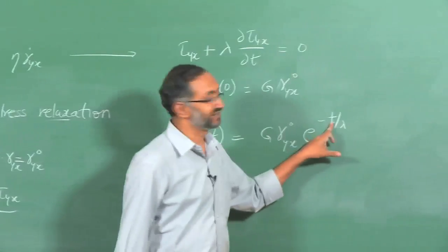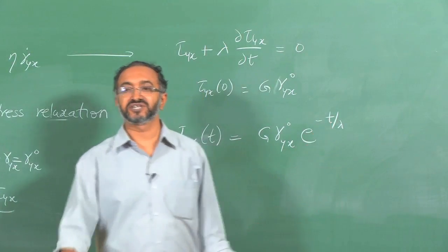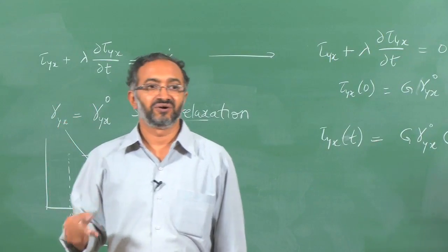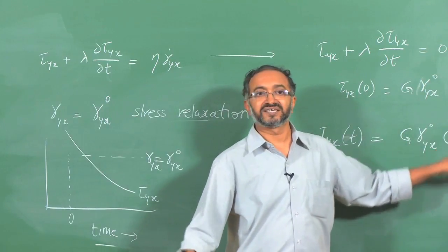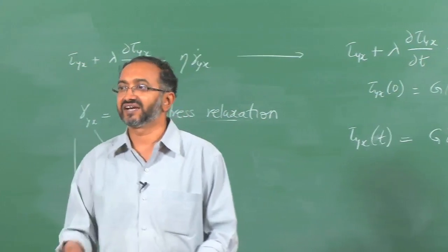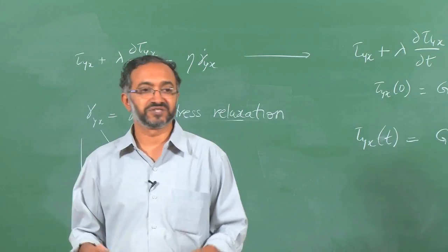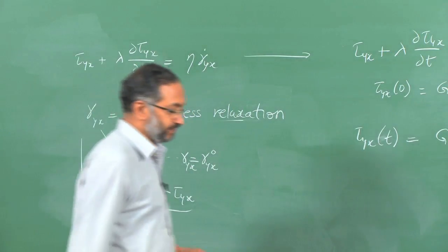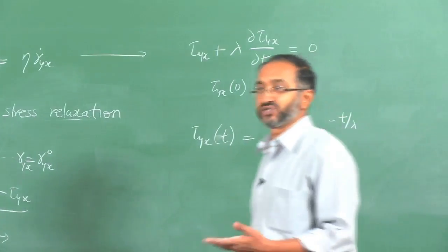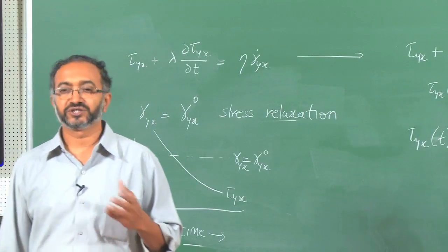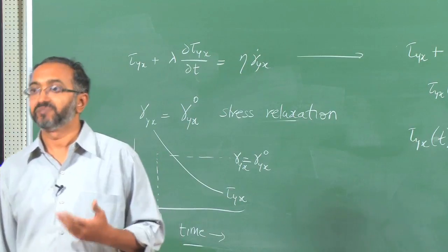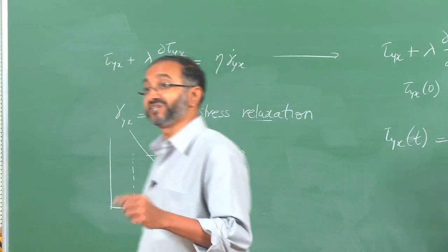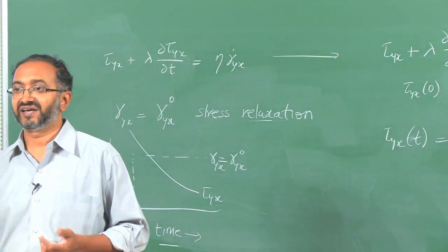The reverse can also be done by changing the time scale at which I do the stress relaxation experiment. I can do the stress relaxation experiment for a millisecond, then for many materials I will observe that all the energy is stored and nothing is relaxed, or I can do the stress relaxation experiment for years, then I will see that many objects which appear to be solid like seem to actually relax stress, and there is some plastic or other contributions which lead to energy dissipation in the material. Something called yielding. Yielding, yeah. So, in case of crystalline solids, yielding is the threshold of deformation beyond which the mechanisms which lead to plastic deformation take place. But what we are talking about here is the deformation is still small, but since we are waiting long enough, that can happen.